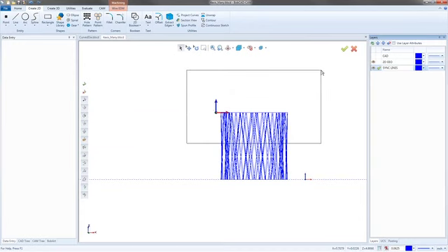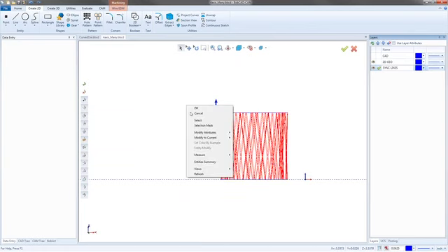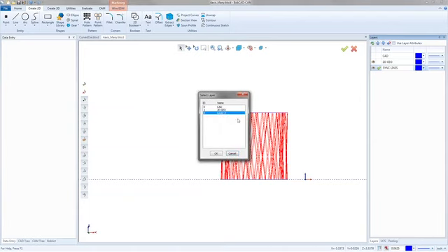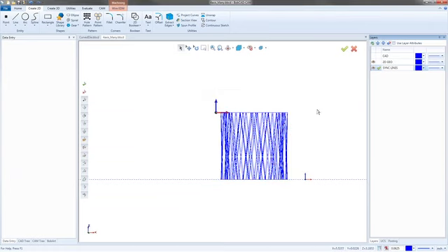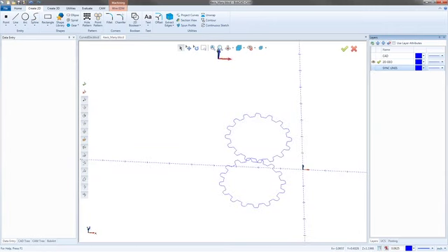Now, I'm not going up and touching the top. I'm not touching the bottom. I'm going right through the middle, small enough that all I'm touching is the lines. Then I'm going to right-click, Modify Attributes, Layer, and then Layer 2. I didn't click out of the box there. You'll see it update in a second. So now if I go in and I turn off the sync lines, it gets rid of those two.